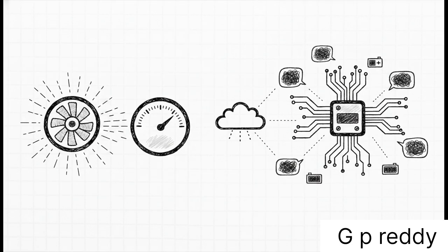Digging just a little deeper into the other two dialects, we have pulse or frequency signals and smart signals. Pulse signals are essentially fast-paced digital clicks used as counters. If you need to measure the exact RPM of a spinning turbine, or say, measure the flow of water rushing through a pipe, a sensor will send a rapid-fire sequence of pulses that the controller counts up to determine the speed.